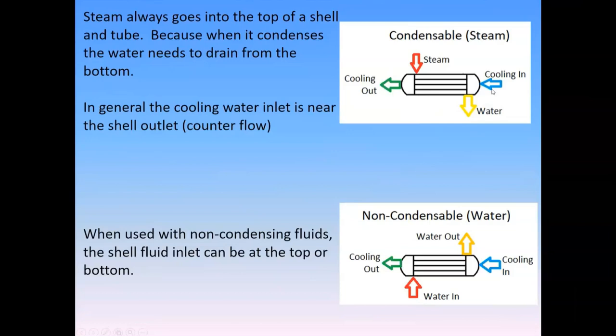Okay, we have a lot of flexibility with how we arrange water, but if we're using something that's condensable, like steam, so if we cool down steam, it will turn to water, we want to be careful with how we're arranging it within a shell and tube heat exchanger.